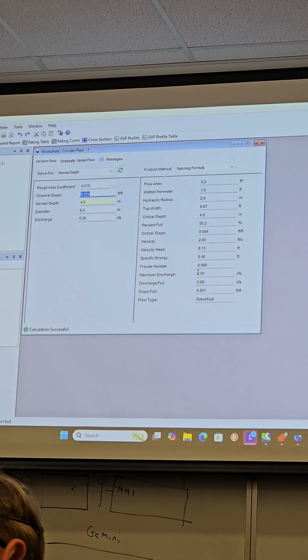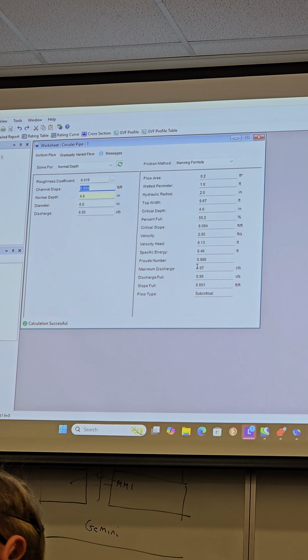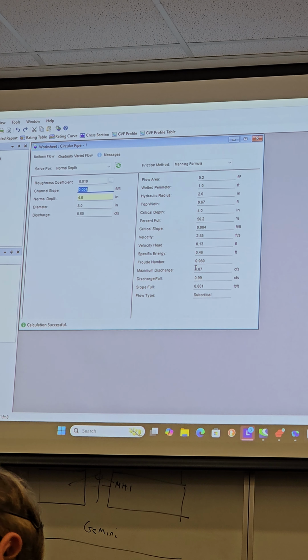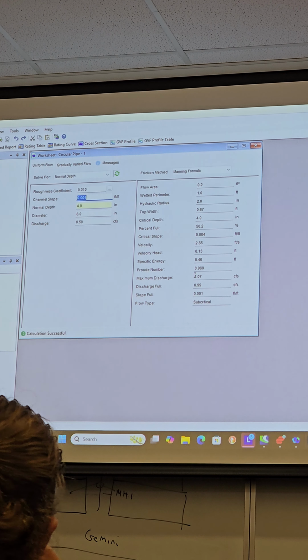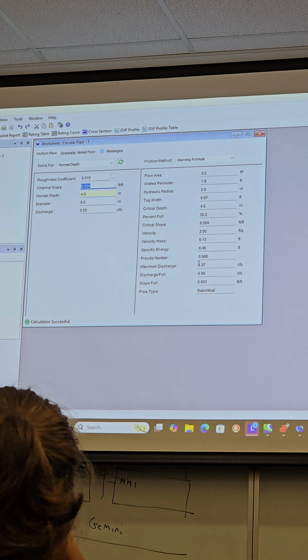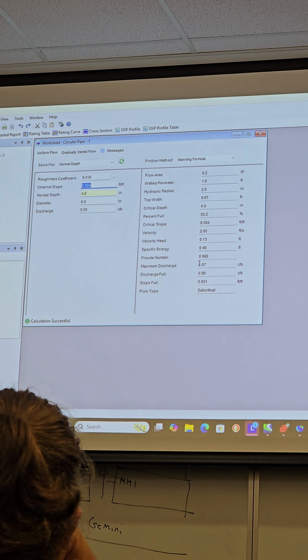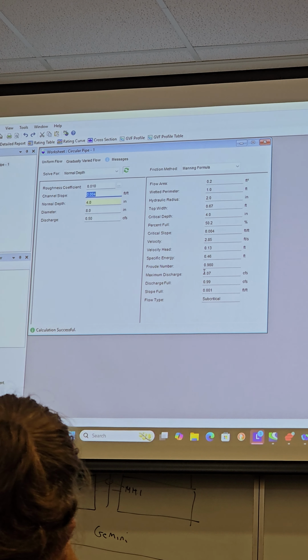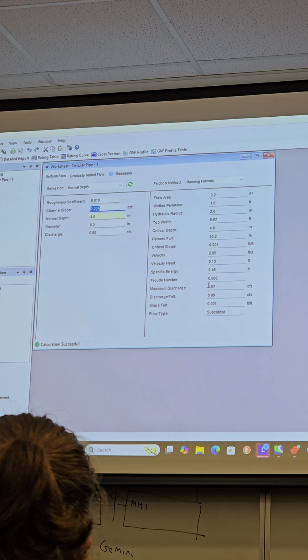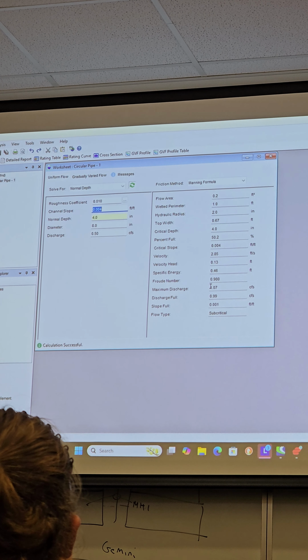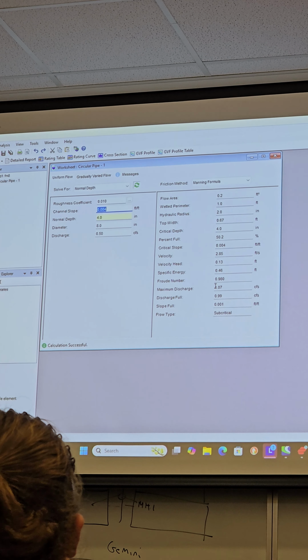You would place your structures in where they need to be located, and then underneath that structure, you might have some type of aggregate to help stabilize the bottom. And then same thing with the pipe. You have to meet specs, you excavate it out, it has to be compacted for the pipe to sit on, and then as you backfill it, you're compacting as you go.